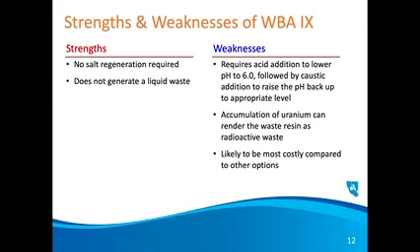The strength of it is there's no salt regeneration required, which is great. In other words, it does not generate liquid salt waste, other than the initial installation backwashing. The problem is it requires a significant amount of acid. Out west, our groundwater is high alkalinity, so it takes a lot of acid to bring the pH back down to 6, and that means it also takes a lot to bring it back up with caustic on the other side of the vessels.